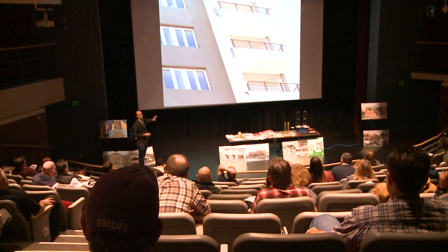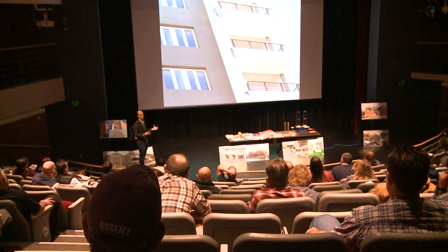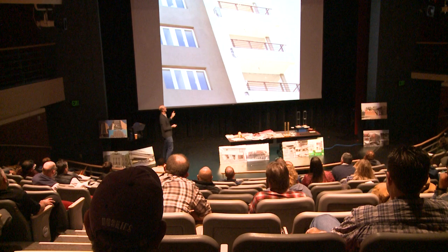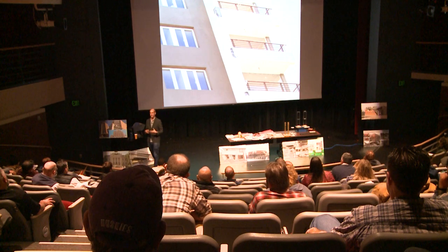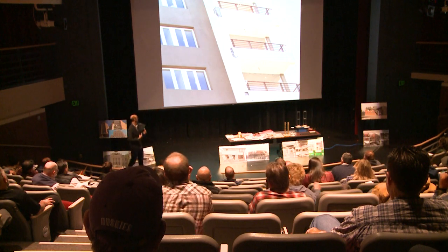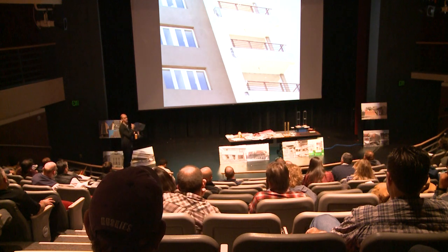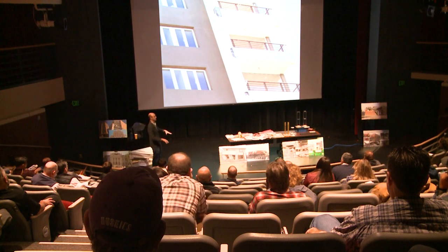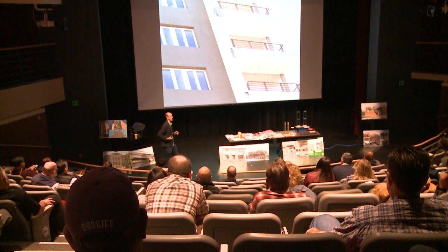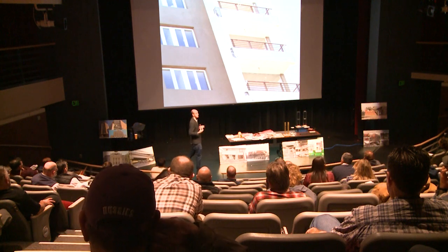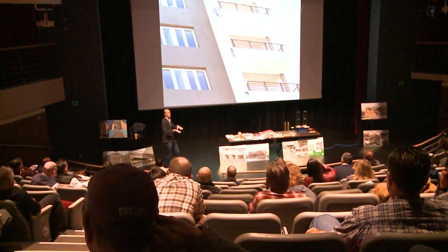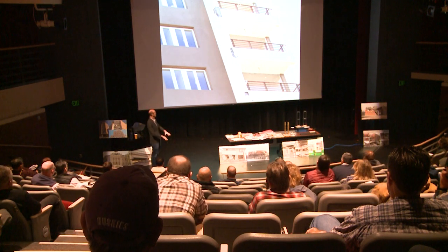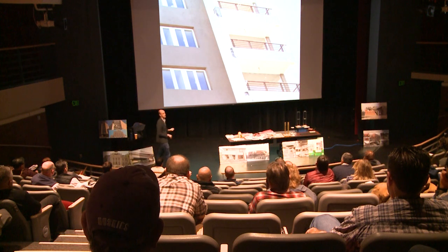Certainly for a high-rise building in a dense urban environment, it's a concern in and of itself, because spalled concrete can be a concern. I think the thing that's interesting about this particular damage, this is total speculation, but there's not really a lot of lateral system going into those. There's just these balconies. So it made me wonder if there was vertical acceleration. A lot of what we've been talking about today has been horizontal motion from earthquake, but there are vertical components, and if there was maybe some resonance with the stiffness of those particular balconies, sort of going up and down and creating that joint cracking.